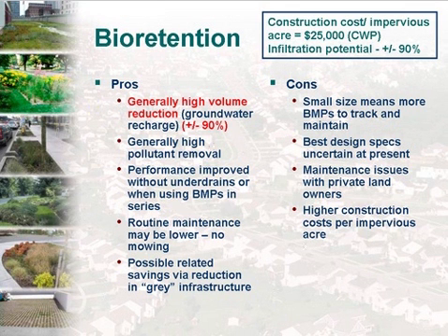I know, John, you had an example, didn't you, of where you had some cost savings? Yes, we have been working on a design for a drainage system in a dense multifamily area. By integrating LID-type facilities, we were able to start our storm drain system farther down in the watershed than without the LID measures in place. So there was associated infrastructure cost savings there, Nico.